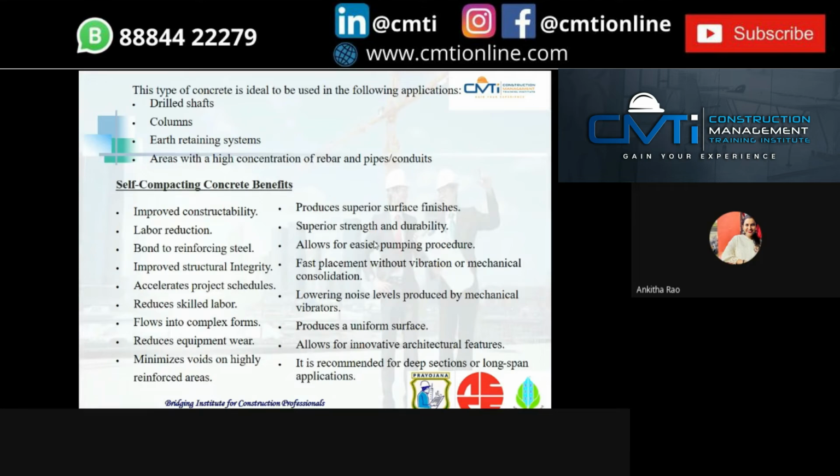Other benefits are bond to reinforcing steel, improved structural integrity, accelerated project schedules, reduced skilled labor, flow into complex forms, reduced equipment weight, minimized voids in highly reinforced areas, superior surface finishes, superior strength and durability, easier pumping, fast placement without vibration or mechanical consolidation, lower noise levels produced by mechanical vibrators, a uniform surface, and innovative architectural features. It is also recommended for deep sections or long span applications.